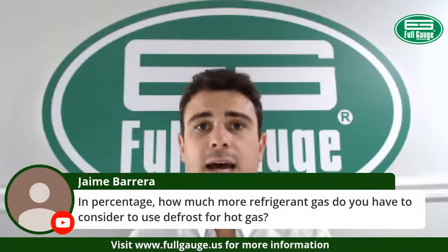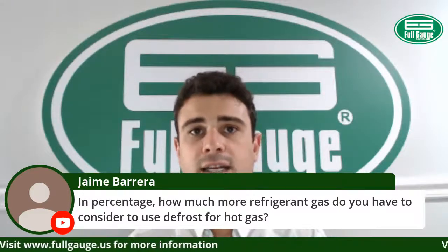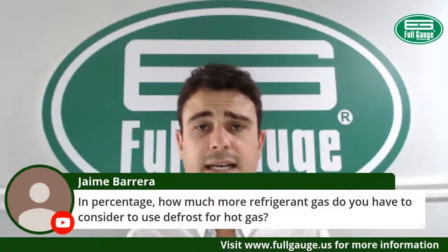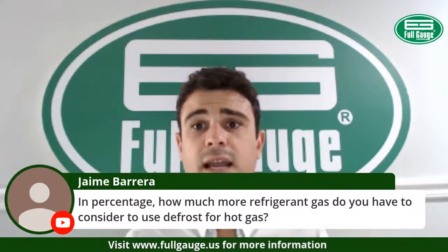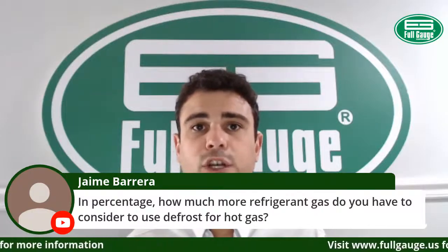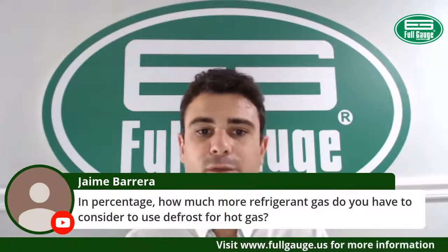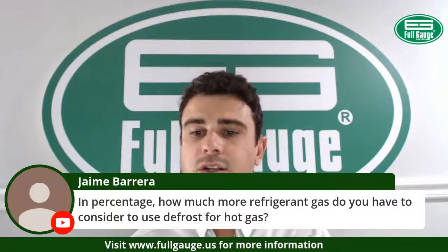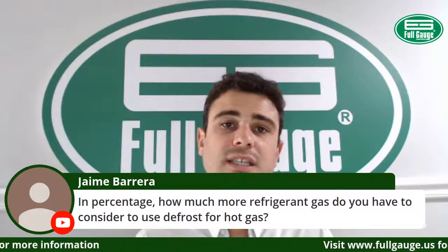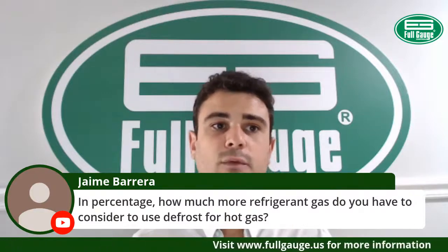There are other types of hot gas design systems. You have a design that uses the normal flow cycle for the refrigerant, and you have a re-evaporator fan after the evaporator. So there are different design cycles, and based on each design, you will have a specific charge.